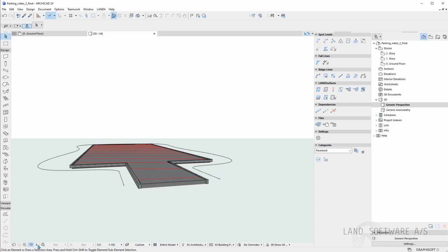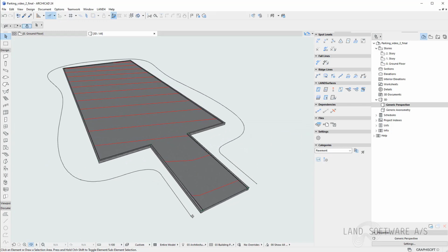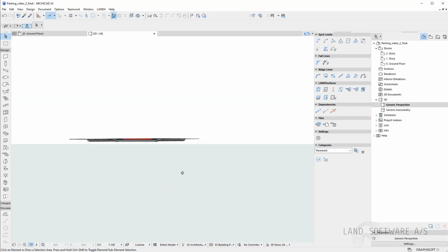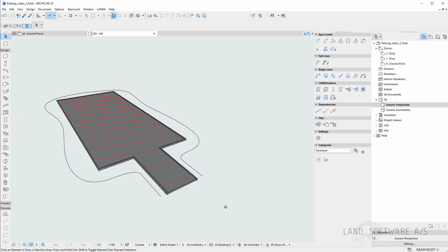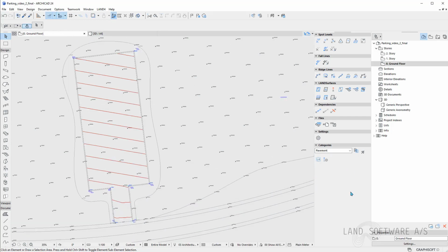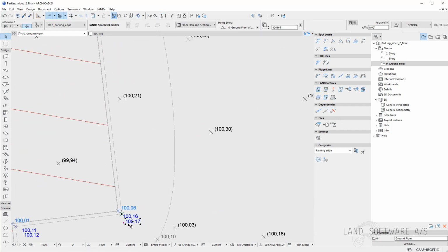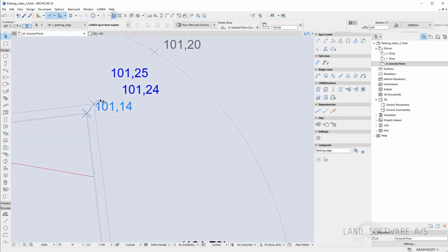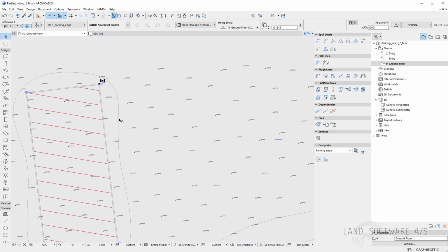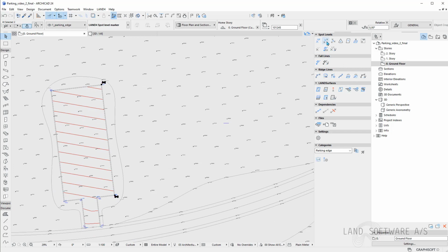And I can now visualize it in the 3D view. And having my outer boundary, I can now start constructing the pavement area. Before I do that, I can actually use more spot levels for the pavement area. So just to exemplify, I will maybe interpolate more points from the parking edge using a simple 2-point interpolation.